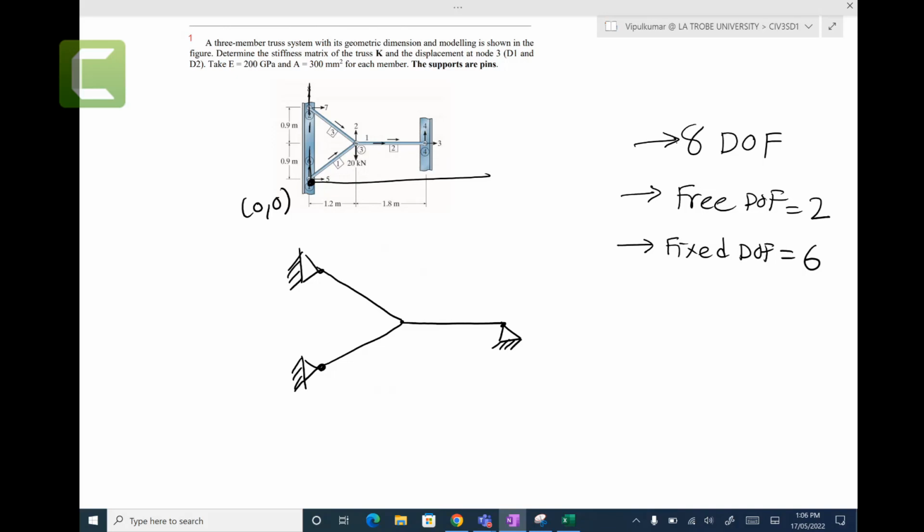Rather than if I take it somewhere here, then this will be negative coordinate, minus, plus, and it requires some attention. Why would I make my life hard by choosing something that is not friendly? Generally it will be given. If it is not given, just take your truss, go far left, far bottom, and pick the point. Okay, so that is your starting point.